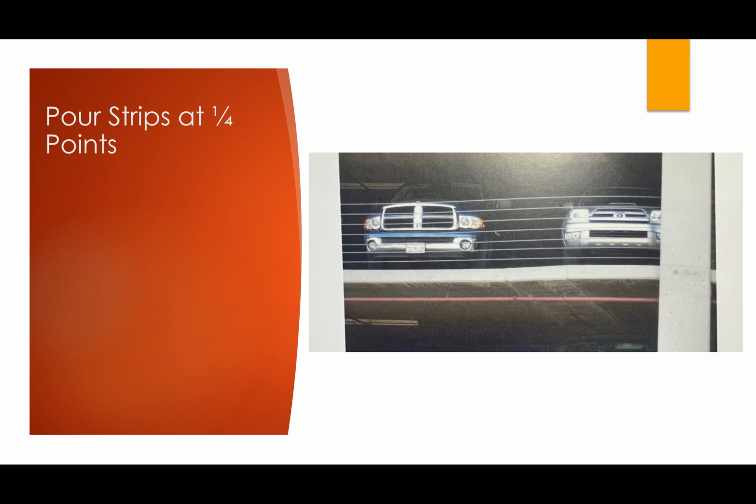Now, obviously, for a parking garage, this probably isn't the end of the world. But again, think of our hotel example, where the finished ceiling in most rooms is generally just the underside of slab that gets painted. And so something like this is going to be immediately apparent in the hotel rooms. So if we're talking a 4-star hotel, you bet there's going to be some explaining to do when this happens here. So that's kind of the textbook reason why they say do not put your pour strips at the quarter points, rather put them at the midspan.